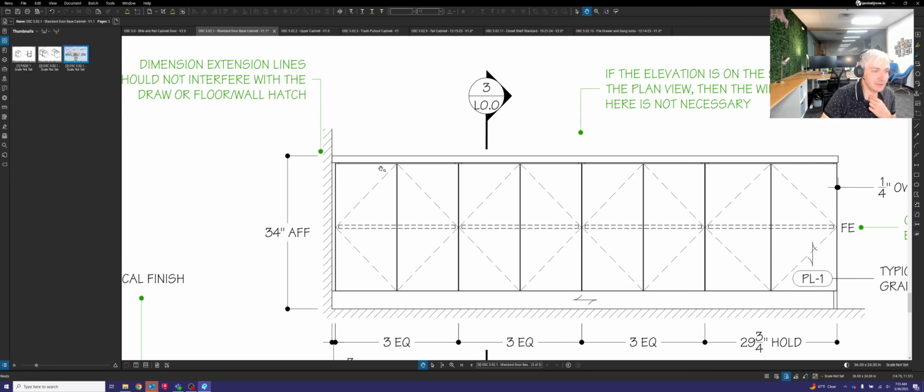They limit the angle of the door as it opens, so you can't open it past 90 degrees, for example. So we'll talk about that in the next video when we talk about hardware, but that's another solution that we have that actually helps prevent drywall damage when a door is sitting next to a wall like this. All right, we are going to switch gears just a little bit.